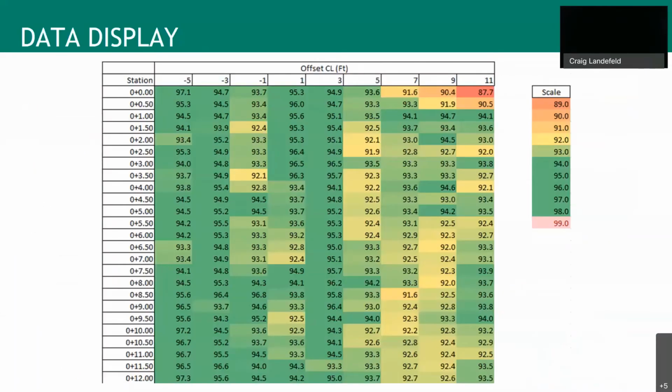As you can see here, this is just a general output from the equipment if you're not familiar with it. The equipment will basically allow you to set different station intervals at which you can report the density. It takes several measurements and then reports the density in different intervals. Here we've got it set to the standard output, which is every 6 inches. You can see the 3 sensors that we have here, and we've made 3 passes down the pavement covering this area. The data just comes out as a CSV. We open it up in Excel.